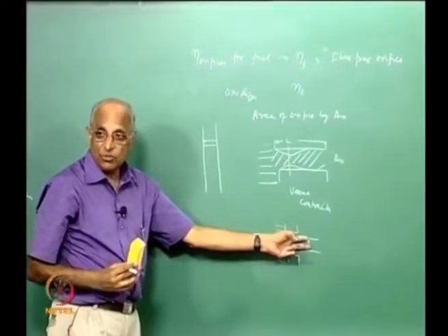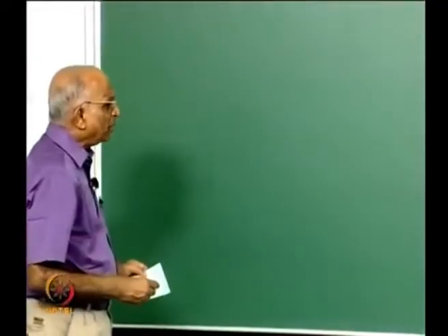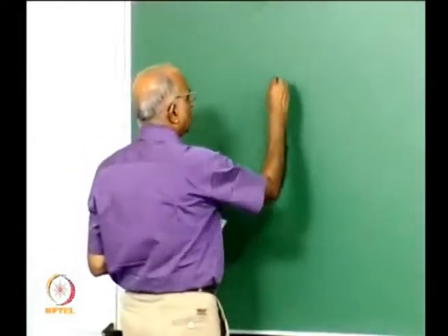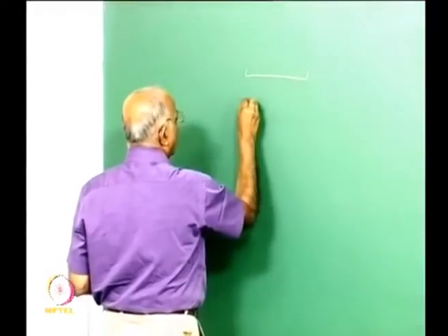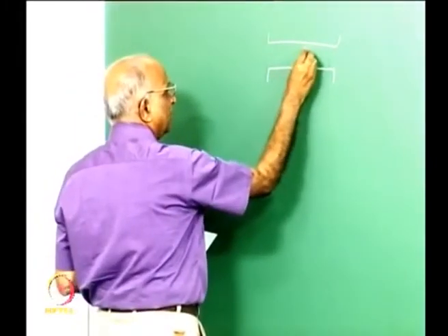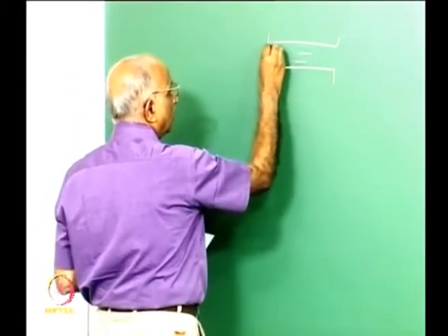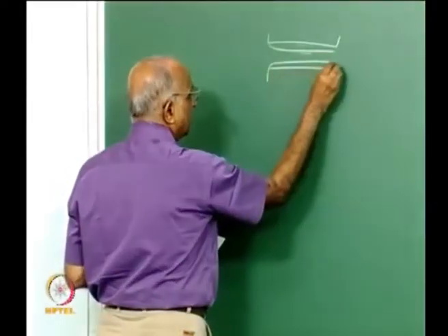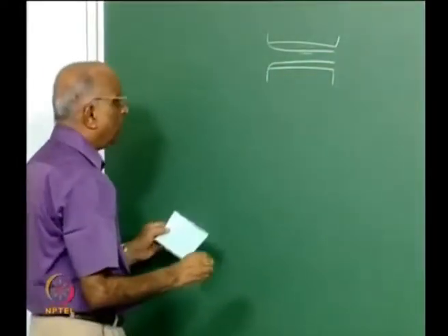Therefore, there are different regimes of flow, depending on the type of flow through the orifice, whether it is fully attached, in which case it runs full, or whether it is detached, in which case it does not run full.